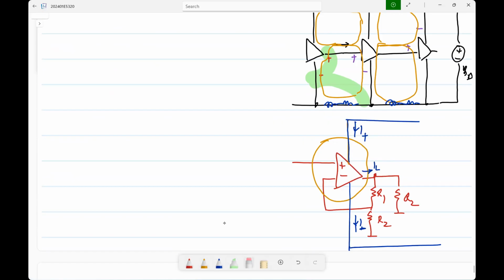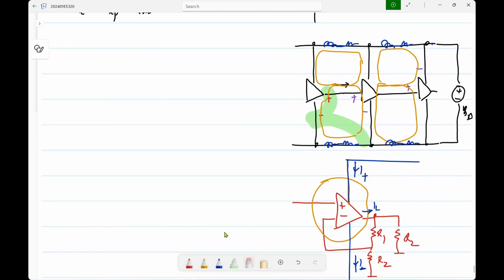So what really happens is if you have a large circuit, there are all these parasitic drops in the supply and ground impedances. So if you are coupling one stage to the other, the idea is the output of this stage is the input of the following stage. But usually the input of the following stage is the output of this stage plus some garbage which is related to all these currents that are flowing, supply impedances and things like that. In fact, it's to avoid this that you use things like bypass capacitors on each stage and so on, if possible, so that this will provide a low impedance path directly here.